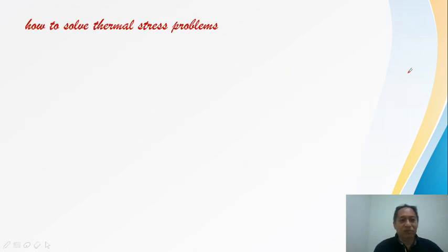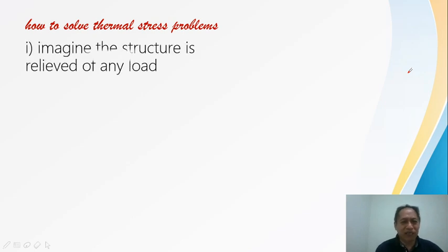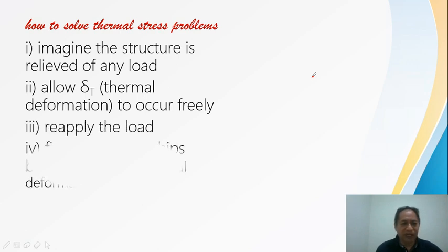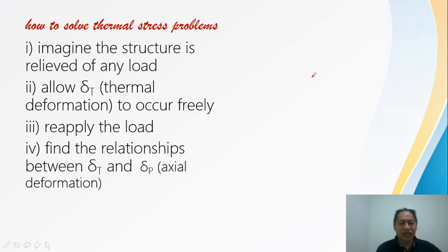Now, how do you solve thermal stress problems? You are given guides. Imagine that the structure is relieved from any load. Then allow the thermal deformation to take place freely. Third, you have to reapply the load and take the relationships between the thermal deformation and the axial deformation.